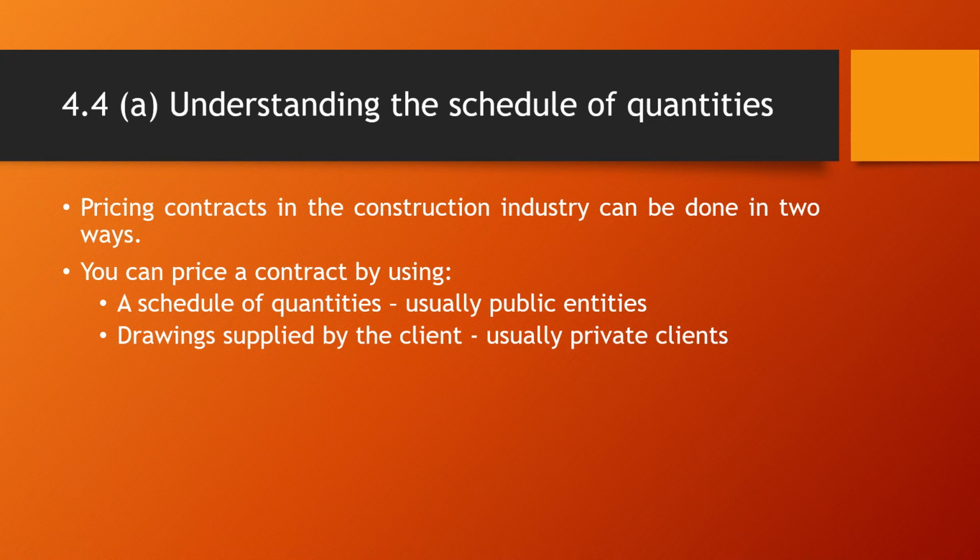And then that client would approach you and give you all the drawings you would need, and he says to you, "Can you quote me on building this house?" Now, what you have to do there is work out the items from the drawings. In other words, you have to draft your own schedule of quantities based on the information available on the drawings. Basically, you take that information and extrapolate it into a schedule of quantities. Now that's a lot of work.